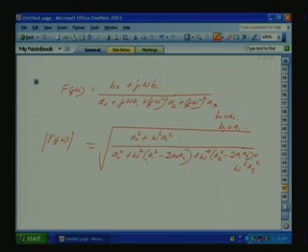So, we will be using this to make the modulus as close as possible to 1 for a wide frequency range. We can eliminate this one, and we can eliminate this one also using the condition A1² is equal to 2A0A2, A2² is equal to 2A1A3. Now, let us use this for our compensation. So, let us write down this condition and our transfer function and then try to do the effect.